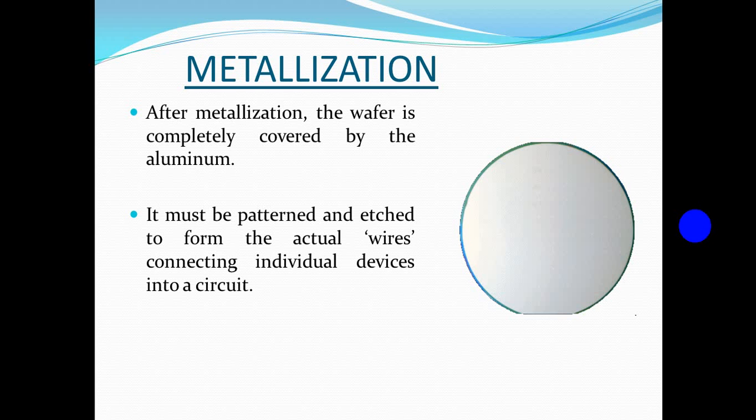How is it done? A chamber containing a large block of the desired metal is suspended above the wafer. The metal will be blasted onto the wafer to form a new surface. The air is sucked out and a small amount of argon is pumped into the chamber. Argon atoms turn into high energy plasma at very low pressure, subjected to high frequency, high voltage. The high energy argon atoms smash into the metal, causing metal atoms to dislodge from the block. Flying into the plasma, the metal atoms become ionized and stick onto the wafer.